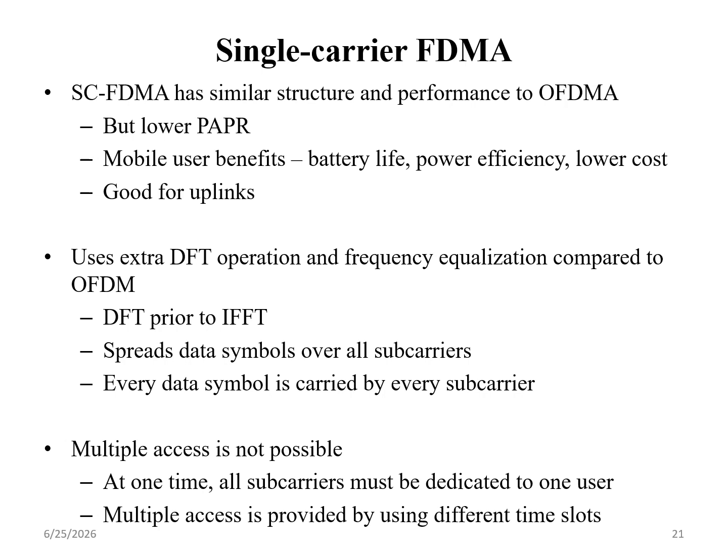Then every data symbol is carried by every subcarrier, so multiple access is not possible. At one time, all subcarriers must be dedicated to one user. Multiple access is provided by using different time slots. So that multi-access is not possible.